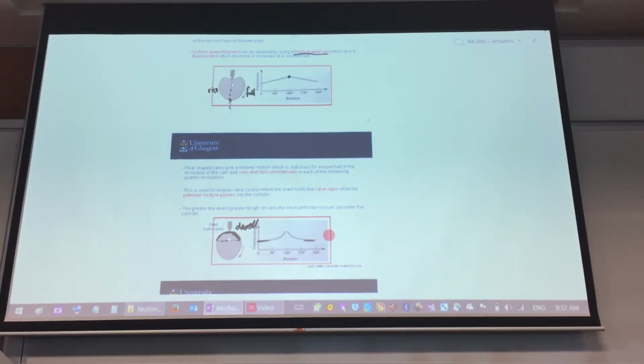How is this possible? You can imagine that egg shape. If I didn't profile it nicely, such that this egg shape is very steep, a super elongated egg, as it rotates, you can imagine when it comes to the fall, it's going to fall suddenly. Falling suddenly means an abrupt increase in your acceleration, which in your profile you'll be able to spot.